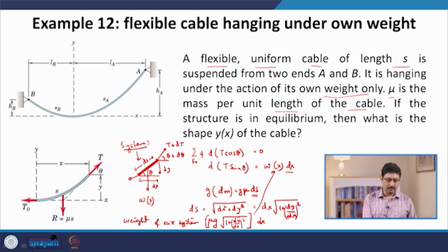This represents the slope of this rope, which you can see from this picture is continuously changing, which means our effective load per unit horizontal length in this example is no longer a constant, but is changing with x. How can we understand this?